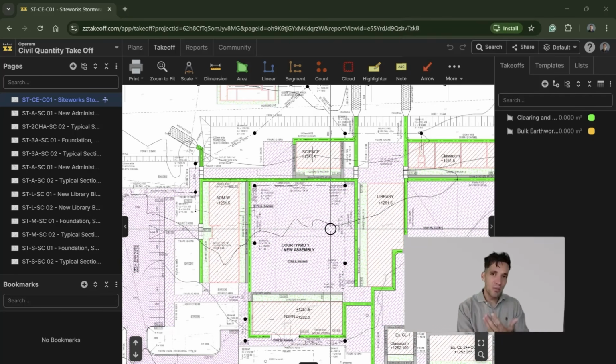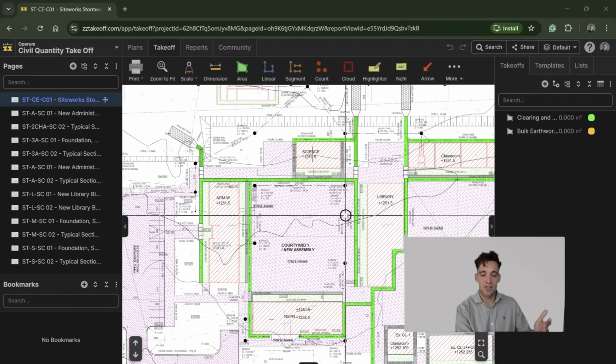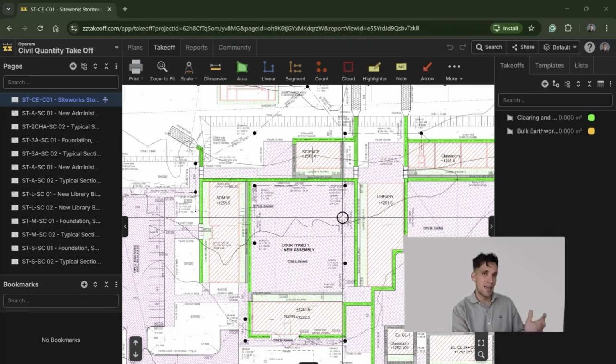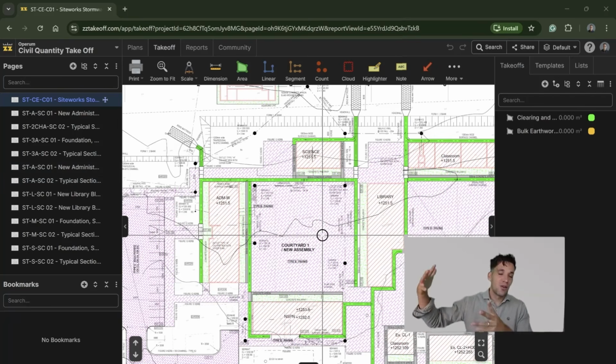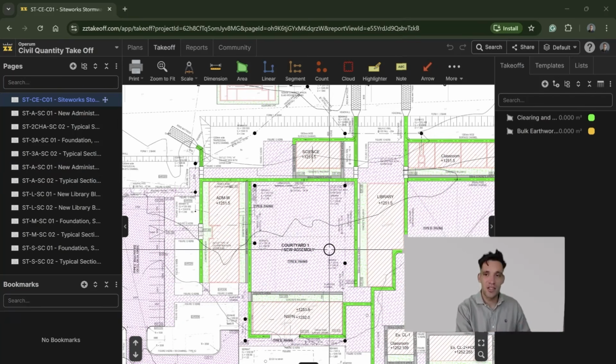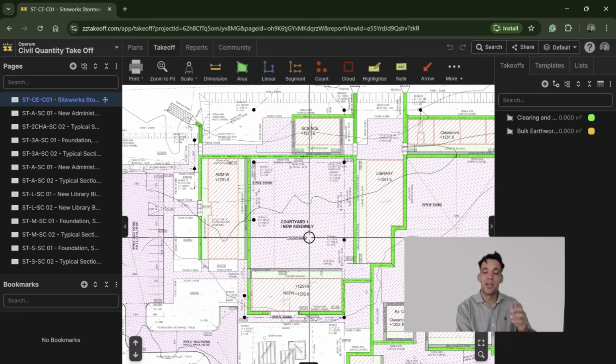But then when we're importing material, we have to factor in the opposite impact on the soil, because we'd be compacting that again. So the actual volume we need to compact in the ground is going to be less than the total volume of soil that we need to import. We might have supplementary specifications which say what type of material we need to import, where specifically we need to buy that material from, and if we're factoring in erosion and sediment control, those quantities typically wouldn't be on the civil design, but we'd have to refer to a separate set of drawings.